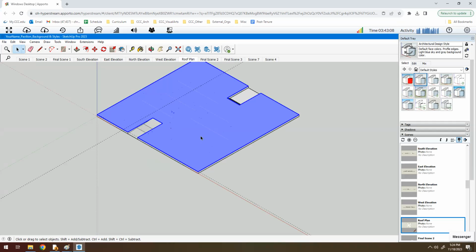All right, now it placed this section plane directly on the ground. And that isn't very helpful because I can't see anything like walls and anything else that happens to be in the view. Typically, a floor plan has a section plane that is about 4 feet above the ground surface or the floor surface. And at that height, you can see things like windows. Windows are normally placed maybe 3 feet above the floor. Of course, there are all kinds of windows. Some go all the way to the ground, etc. But generally speaking, a 4-foot section plane is where they are typically.